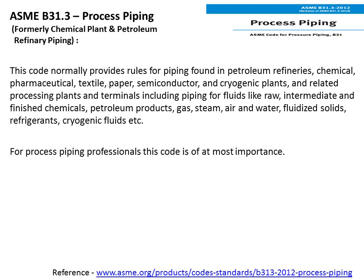Next is ASME B31.3. It was formerly called Chemical Plant and Petroleum Refinery Piping. This code normally provides rules for piping found in petroleum refineries, chemical, pharmaceutical, textile, paper, semiconductor and cryogenic plants and related processing plants and terminals, including piping for fluids like raw, intermediate and finished chemicals, petroleum products, gas, steam, air and water, fluidized solids, refrigerants, cryogenic fluids, etc. For process piping professionals, this code is of utmost importance.